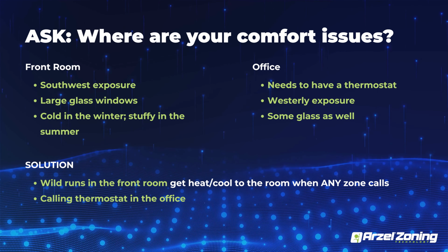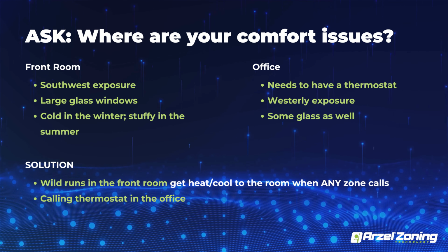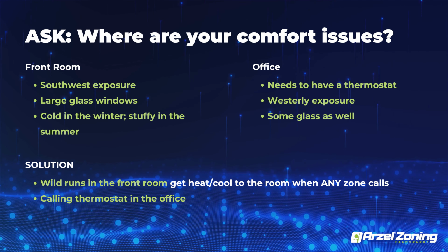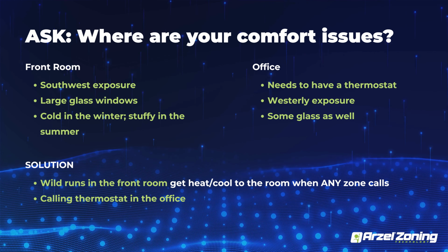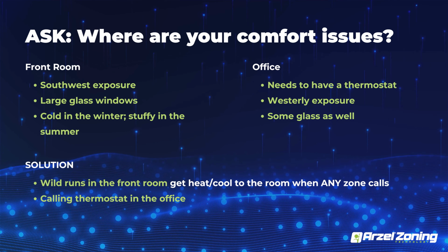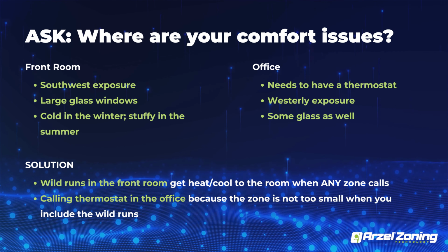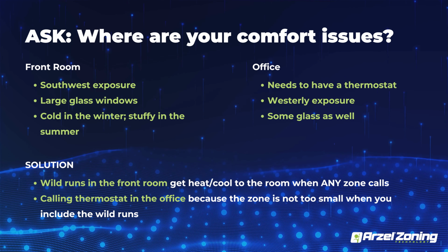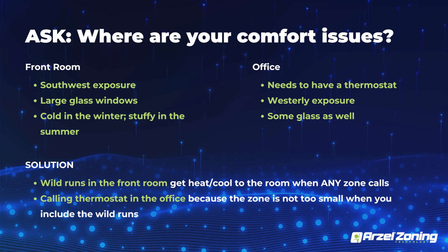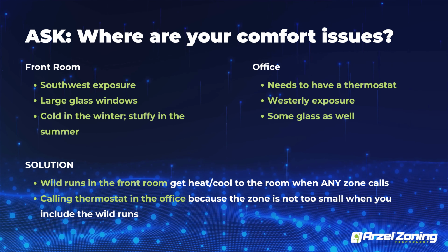I could give him a calling thermostat that could give him heat on demand, cooling on demand, because my smallest zone was not one 6-inch run on a 4-ton system. It was one 6-inch run with two 7s up high and two 7s down low. My smallest zone wasn't any longer too small. You see what I did there? So you can do things like that, and it prevented me from ever having to even put a bypass on the system.